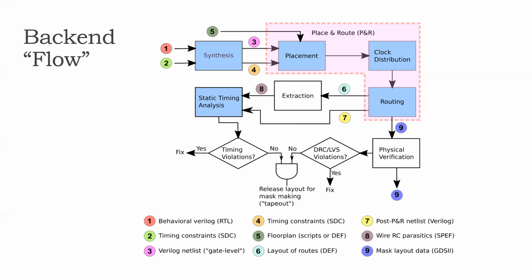And in order to be able to do that logic restructuring, the placement tool also needs to be aware of the functionality of each cell in the library, and that it gets by reading the .lib. So the placement tool has to read both the .lib and the LEF. Okay, the .lib will be used to be aware of timing as well as to do any logic restructuring if the placement tool is capable of doing that.